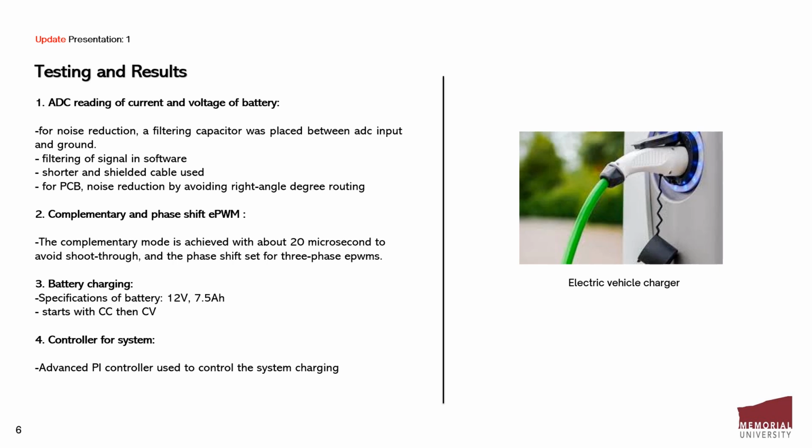So we needed an ADC reading, and to reduce the noise we use a filtering capacitor as well as shielded cable, and also shorter cables.